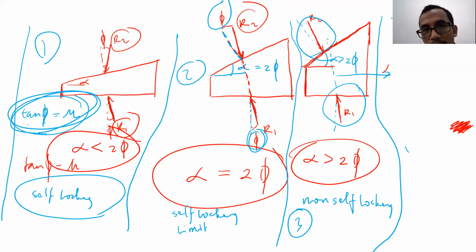Because in the CL before, the wedge is 10 degrees, right? And I use 10 degrees for the normal force and the friction, and then just sum Fy with sin 10. The wedge is 10 degrees means the alpha is 10 degrees, right? Yes, so alpha is 10 degrees. There is no relation between alpha and phi. Phi depends on the mu.